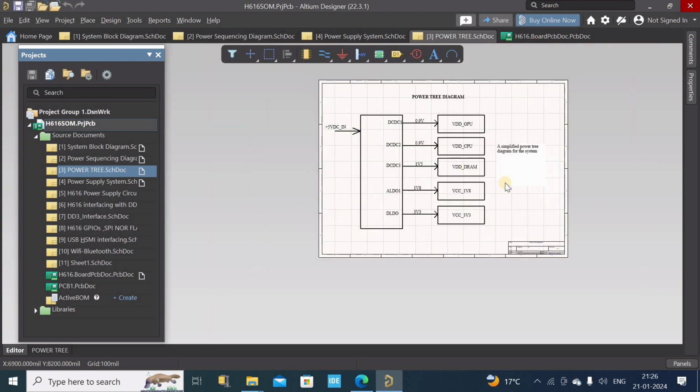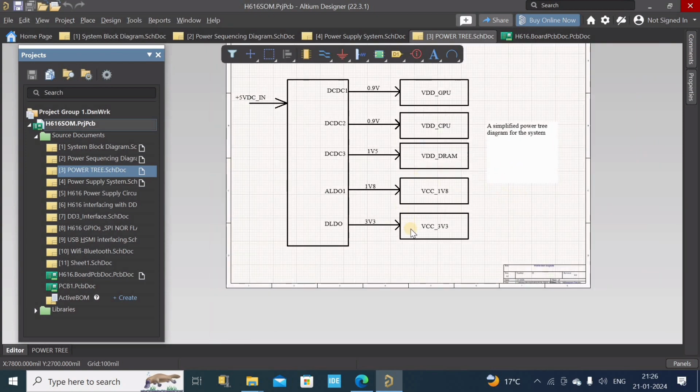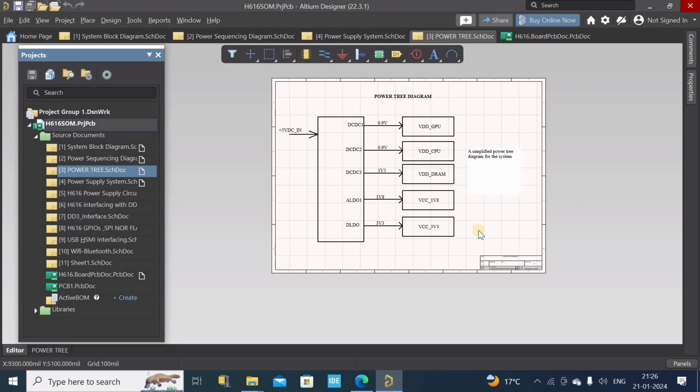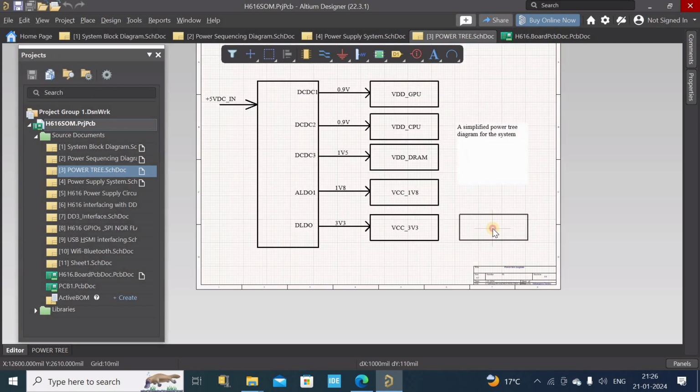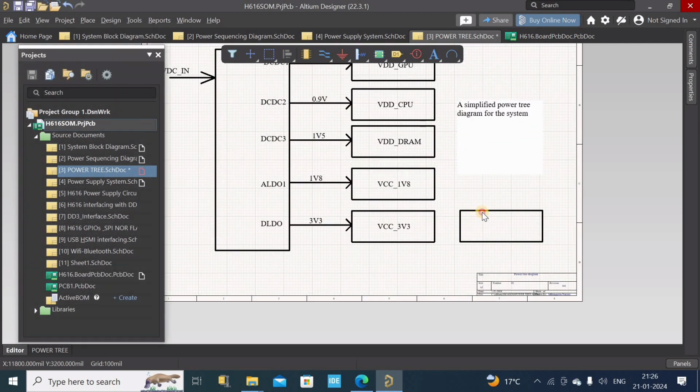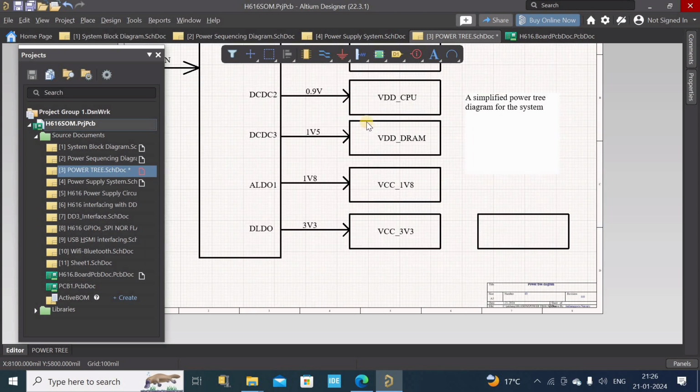We can also create one sub-branch of this part 3 for my VTT regulator. So let me go ahead and create it right now. So okay, I can copy this, copy, and then paste. Alright, this is my VTT regulator for VTT, the termination resistor voltage for the DDR3 interface, and then also DDR3 VREF, I mean reference voltage.